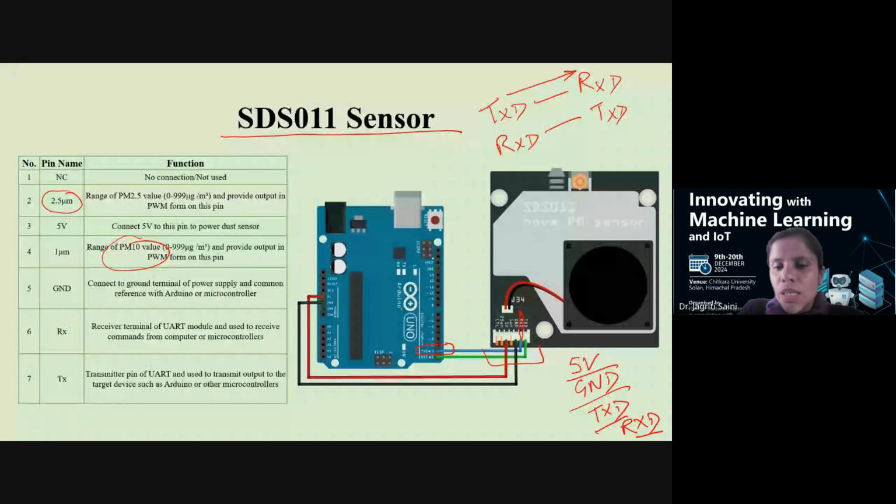And then the last one here, the green one, is your receiver pin, and the first one here is the TXD. So accordingly it is connected. Whenever you have a sensor that works on TXD and RXD, this is the same technique you follow, the opposite connection, so that the communication line can be completed. Because if one transmits, only then the other receives, and the same goes for the other side. The acknowledgements will be received with one as transmitter and the other as receiver accordingly.